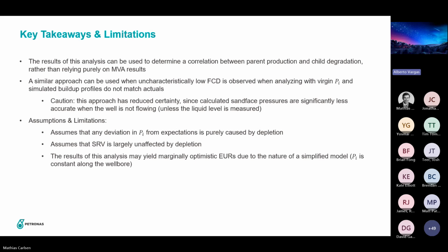And then the last note is that in these analytical models that we're running, we have a single reservoir pressure assumption, so the EURs derived from this methodology can be a little bit optimistic. We have portions of the wellbore that are likely more depleted than others, and averaging that out into a single reservoir pressure means that as we increase the drawdown, we'll have more contribution from more parts of the wellbore, and so it'll give you a false increased LFP for a period of time. Yeah, so that's the overall workflow.